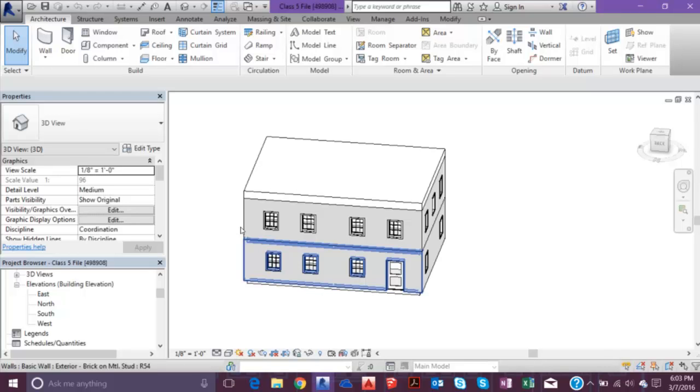and all. And so what I'm getting at is when we get our models like this, they'll come like this from the architects and the engineers, and they'll be at a real macro level. We can break them down so we can do our more accurate estimates off them. We can do them with just the walls or the floors or the ceilings and all that, but we have to incorporate formulas to make up the quantity of, say, your studs and your drywall and your sheathing and your exterior and all that stuff. So instead of doing that, Revit will allow us to make the parts with the model.